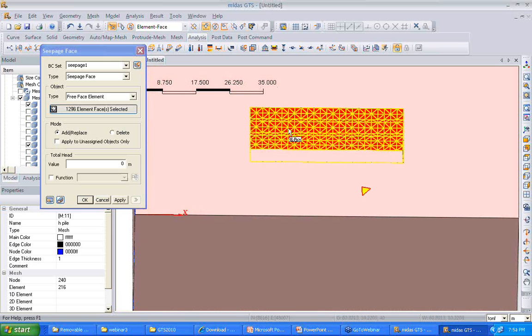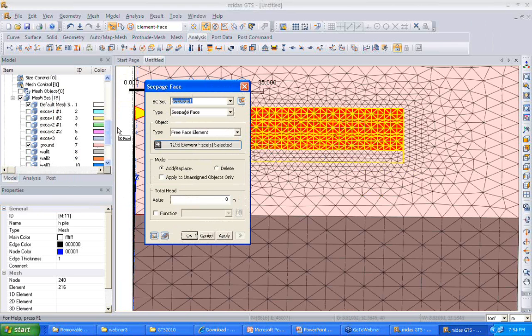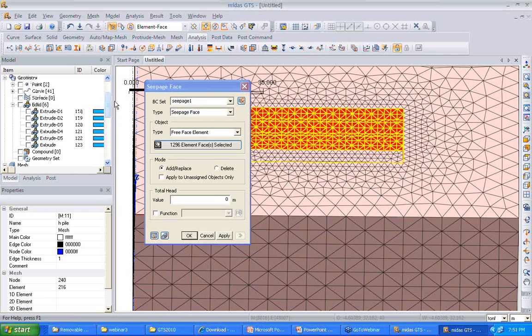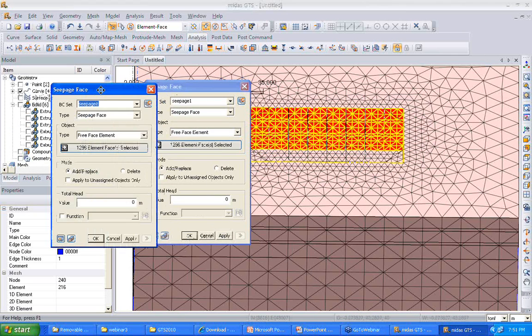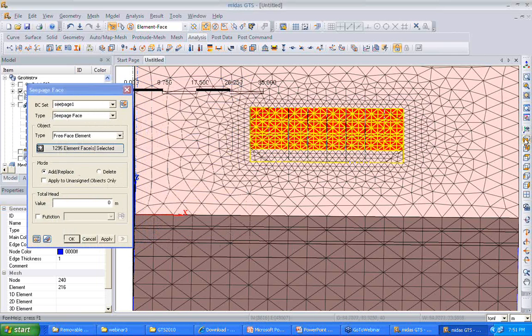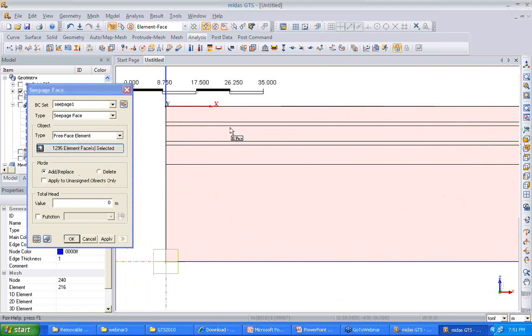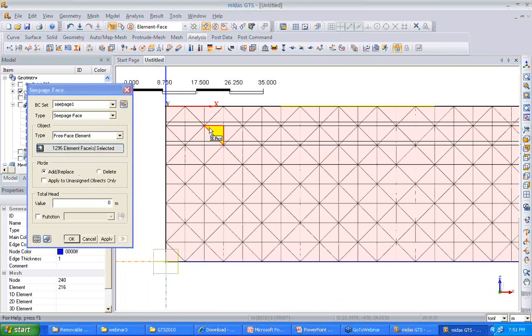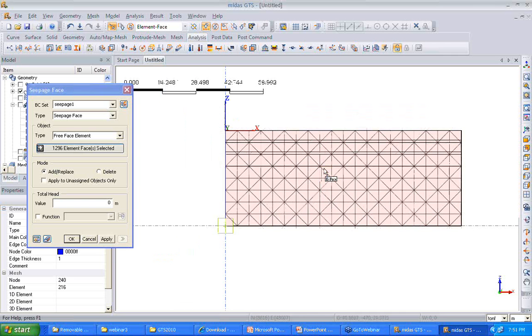But this is for the whole depth. All we need to do is activate the seepage phase corresponding to a required depth. So the cheat code I will be using is the curves which we use to create the dividing surfaces. The first two curves correspond to excavation stage 1.